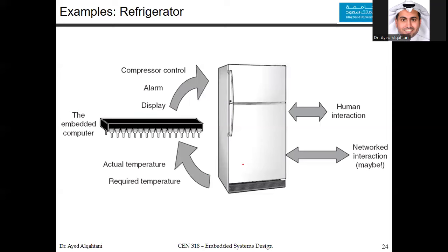The machine clock frequency, which is denoted by FOSC, or the frequency of the oscillation, is the rate of the clock oscillation in a single second, which is usually measured in megahertz, sometimes in gigahertz, and it's referred to as the oscillation frequency. Now, related to the FOSC, we have the TOSC, which is the machine cycle, which is basically the elapsed time for the system clock to repeat itself.